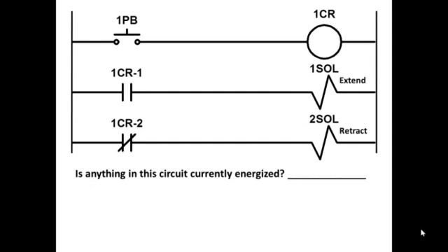You have live voltage on the two vertical lines. So over on the far left, that vertical line is the hot of power, and the one over on the right, the vertical line, is neutral. If this were a 120 volt circuit. If it was 24 volts DC, you probably have plus voltage over on the vertical line on the left and negative on the vertical line on the right. So following the path for current flow, do you see a complete path?